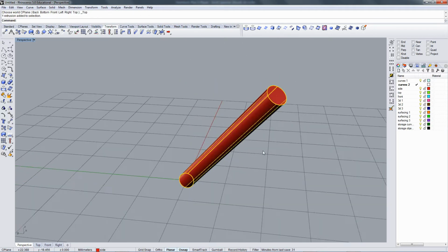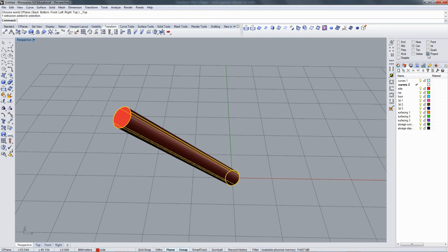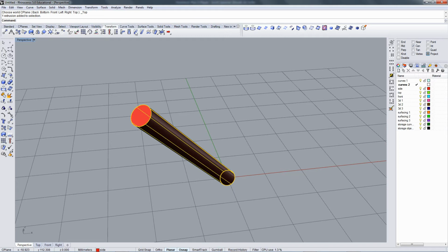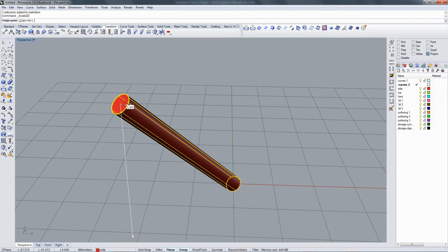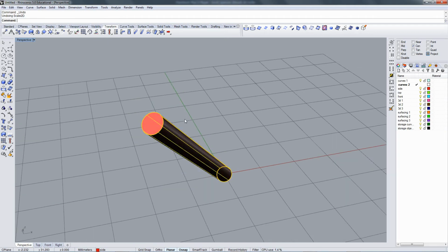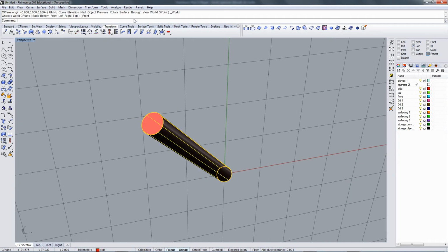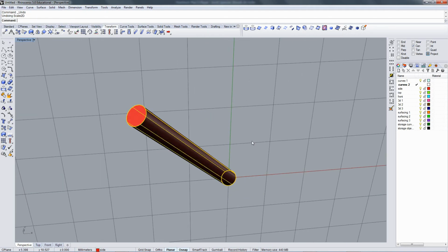Okay? Now, some advanced Rhino people out there will go, well, what if I project it to the C-plane? This will project my pick points so they don't go out into three-dimensional space. See, it projects it down. Well, that's not going to work because, for one thing, it's going to change where it scales around. But it's going to also give you the same problems. Okay? Can't be done. Alright?